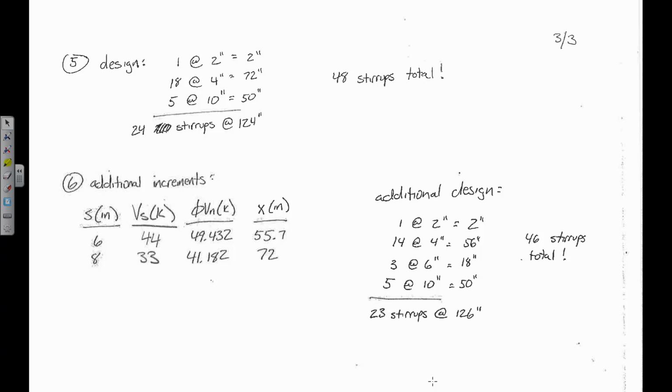It's just a simple way of ensuring that we have a stirrup that crosses the support. So watch this. Let's say here's a beam, and I use 4-inch spacing everywhere. That's enough. I don't really feel like drawing anymore. Now, that beam goes on forever, right?